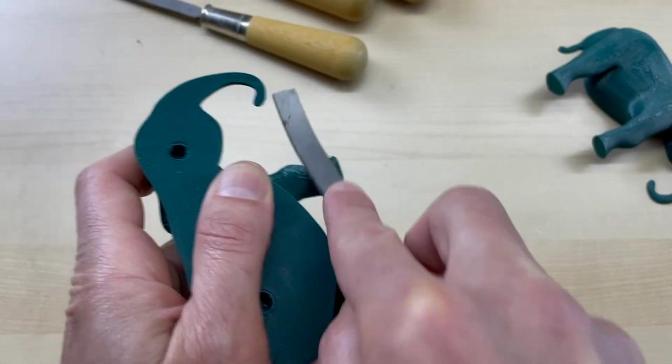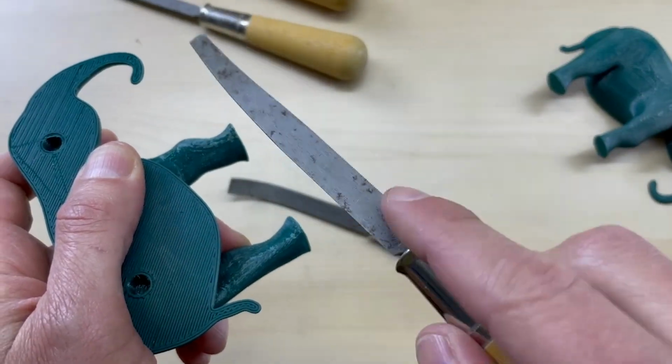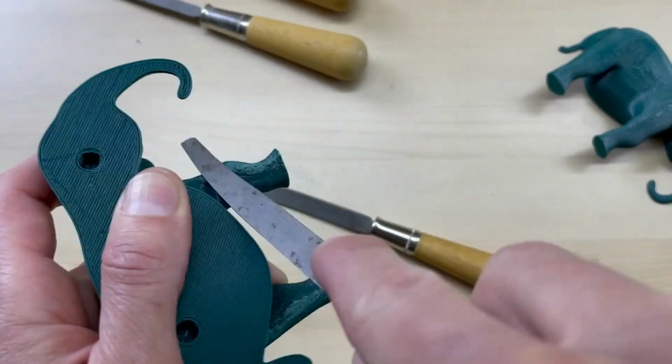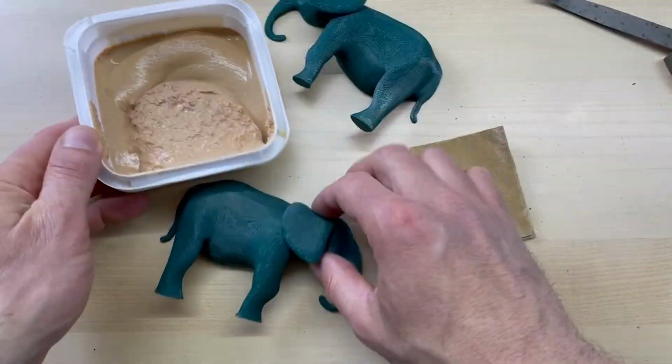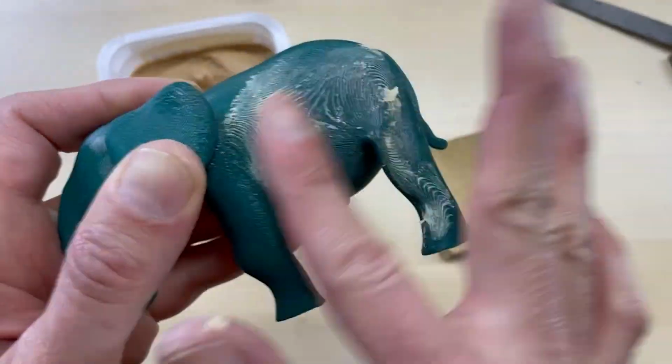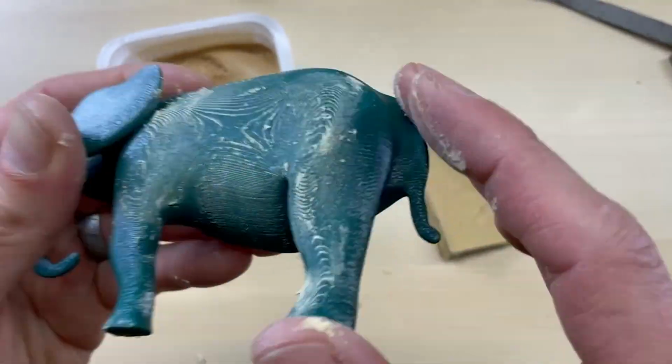There are a lot of techniques I could use here, from acetone to melt the material a bit, to filler primer and a bunch of sanding, but I'm going to try something I've never done before and use wood filler. I'm not sure how it'll turn out, but I'm eager to learn. As you can see here, I'm just putting on enough to fill the low spots between the layers.